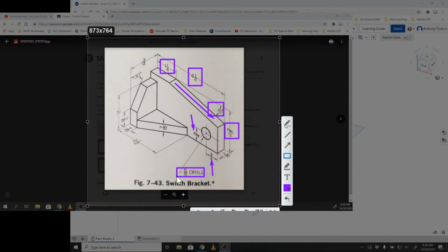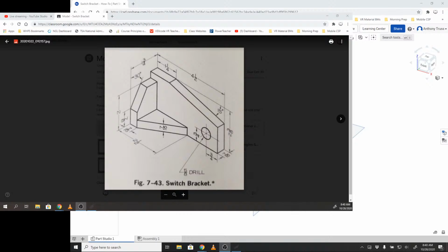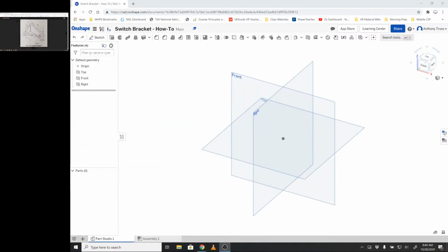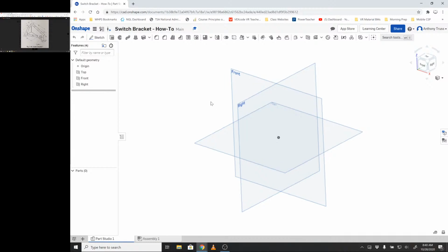Okay, so the first thing I'm going to do is make a rectangle on my front plane with 4.5 inch width and 2 3/8 tall measurements for the rectangle. Okay, and then after that I'll be using the other values. So we'll come back to this to get some information as we create. I don't want you to not see me do that on the screen and be wondering what specifically we're doing. So at this point, I already have my front plane here.